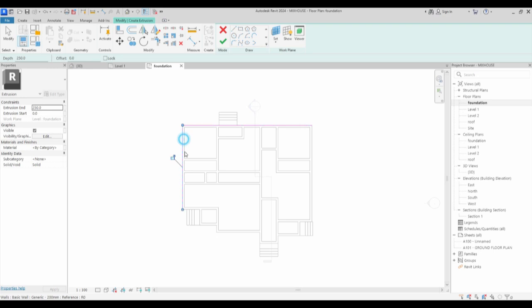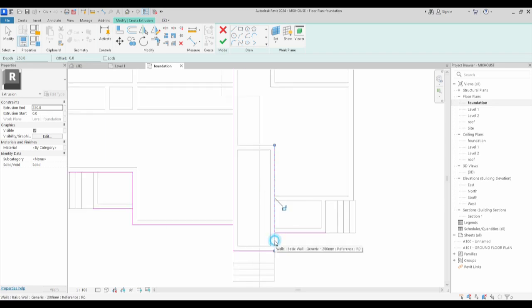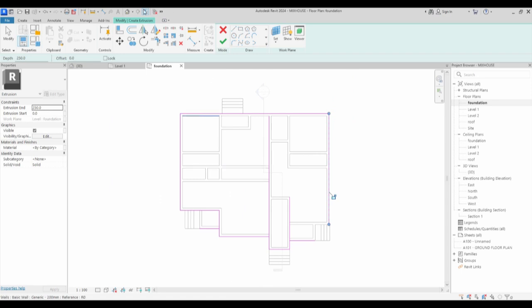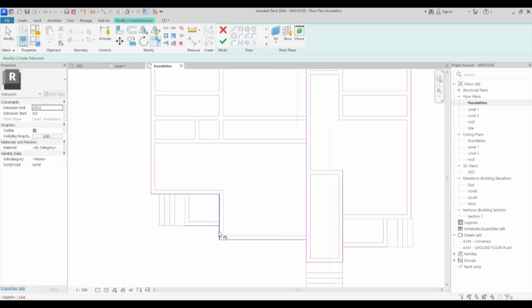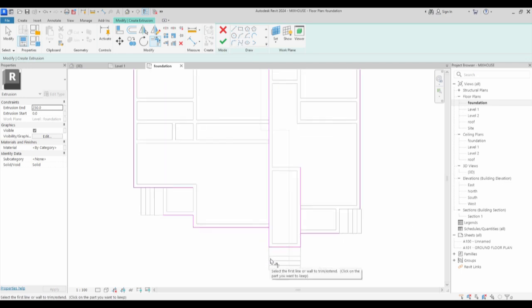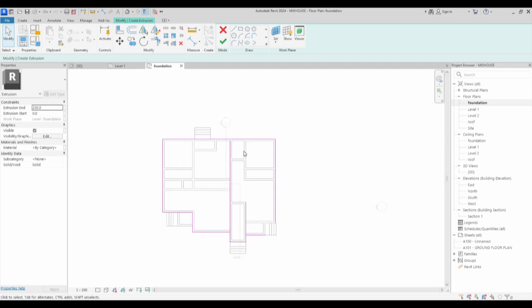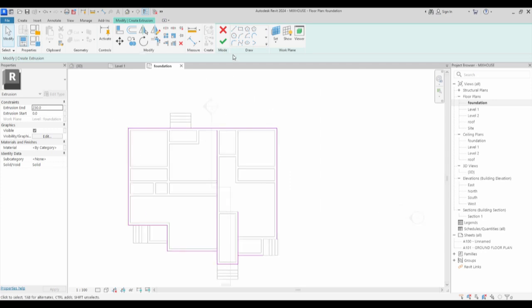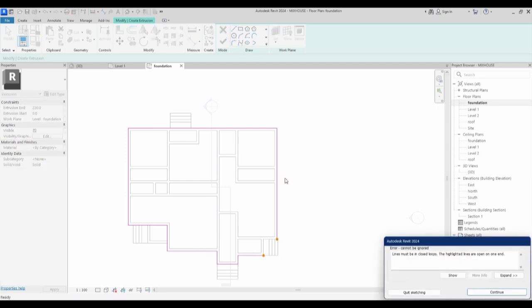You click here, select this, select. The benefit of selection is that, though you can draw this bit line, they allow you to quickly pick up the center position of whatever you are doing. In other words, this will quickly give you the idea and the detail that what I'm doing now is done in a realistic manner, such that there's no contradiction to the line of references. Instead of me putting lines one after the other, sometimes you connect, sometimes may not connect. That is why I'm using pick line of the external wall. You click, that is the simplicity.